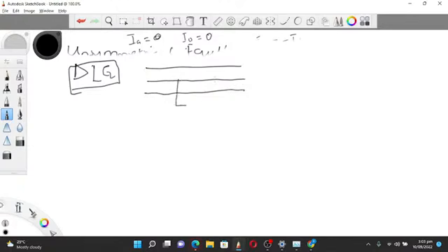So we have IB, sorry, we have IC, and then it's to ground. So we always put, if there's a ground, the fault impedance at where the ground is. And here is IB, here is IC. This is phase A, phase B, phase C. From here, you can see that the current coming here will be IB plus IC, through ZF.